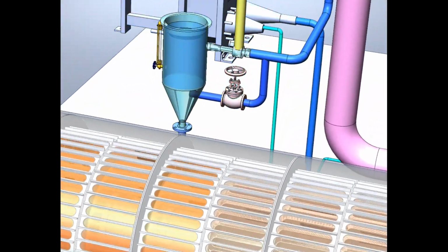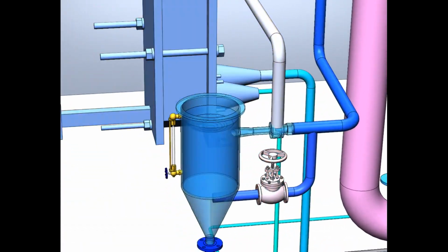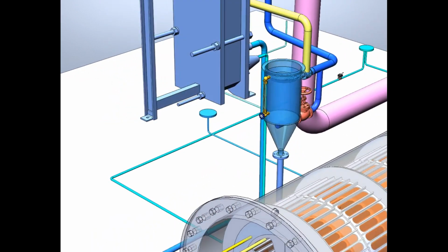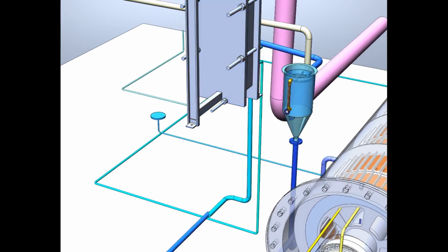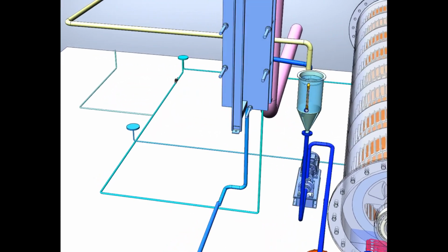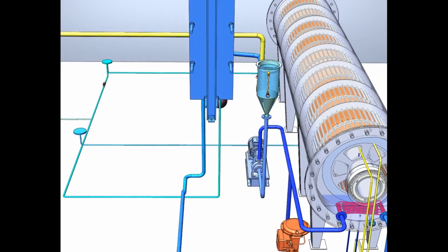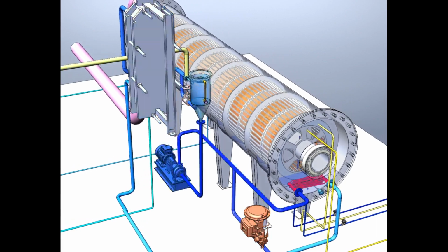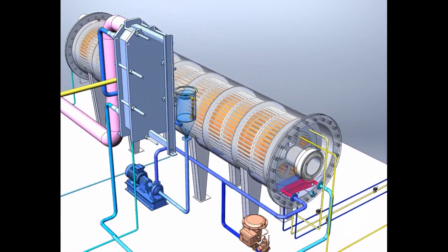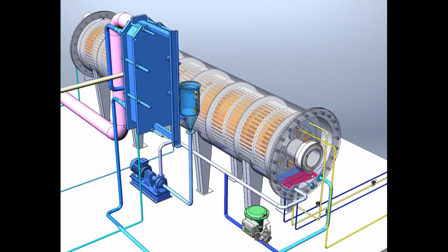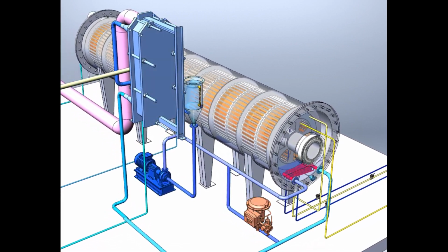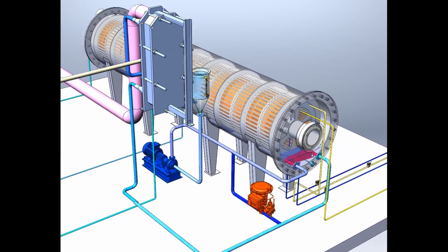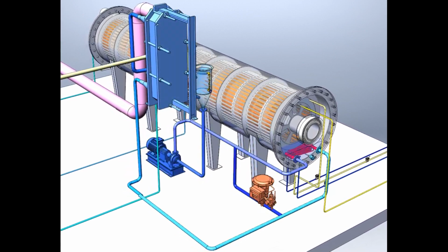Next, the heated coolant under a pressure of 0.3 megapascals is sent as a working fluid to the ejector, which ensures the creation of a vacuum of 2 to 6 kilopascals in tanks for collecting light water. The water-air mixture after the ejector enters an open tank from which water is pumped out by a circulation pump, and air is discharged into the environment. Thus, with the help of this circuit, a cycle of steam generation and its condensation is provided without the involvement of extraneous sources of thermal energy, which makes the separation technology energy efficient.